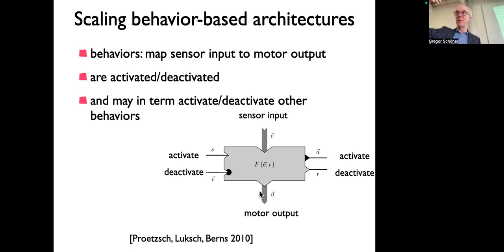If the output of this is a distance, and some other module has that as an input, then they can be chained that way. This is what was originally called subsumption by Rodney Brooks, that a module can get its input directly from a sensor or from some other function that provides that same kind of output. That's how you could make more complex architectures where there's some sensory flow.